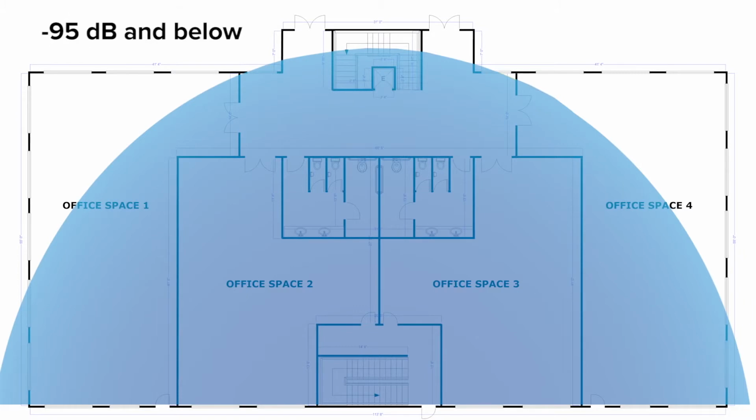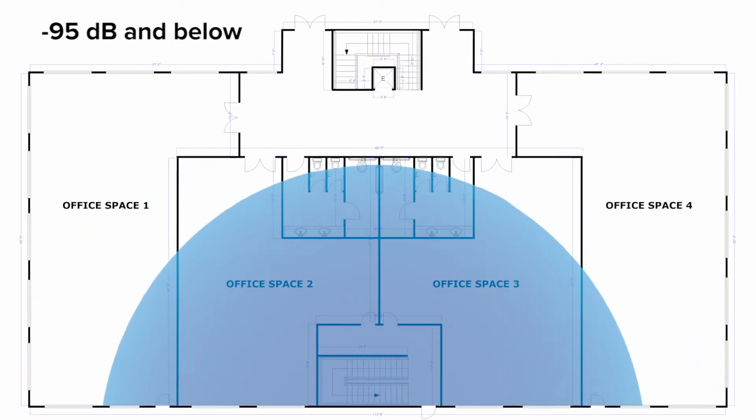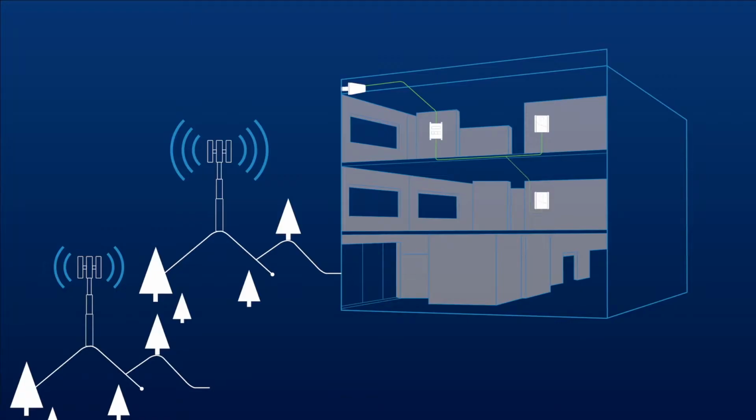Negative 95 dB and below doesn't leave you with much signal to work with. A signal amplifier system will still work, but your coverage areas will be dramatically impacted. You'll need to experiment with adding boosters and the placement of antennas to fulfill the customer's needs.